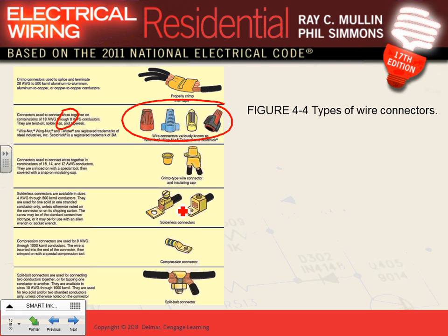And the other things, guys, the notoriously famous wire nuts are easy, but I don't know how many of you guys are familiar with the crimp ones. You can get this one up to 500 kcmil. Typically, the cheapest way to use these, the wire nuts is easy. You see them in the box. But with these, if you have a gutter, and if you bring a feeder and you want to tap from this feeder to feed multiple things, that will be a good application for these crimp connectors, where you tap a 500 conductor into a 500 kcmil conductor, tap from it a 250 kcmil conductor to go to a different panel.